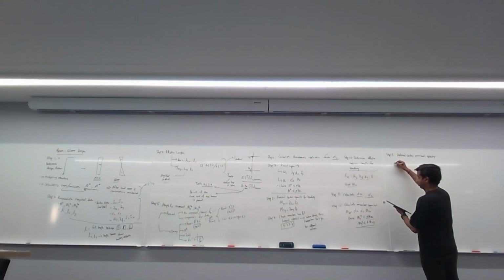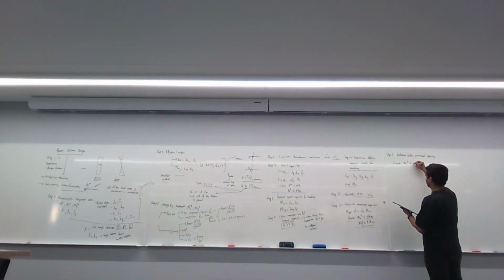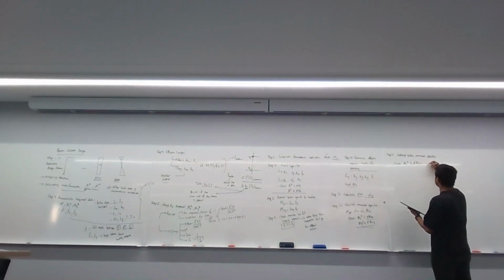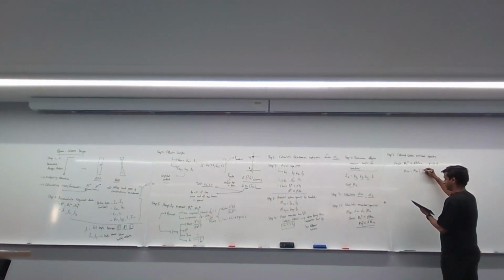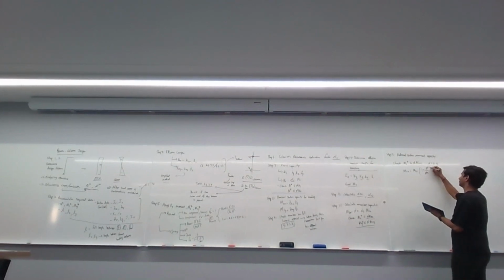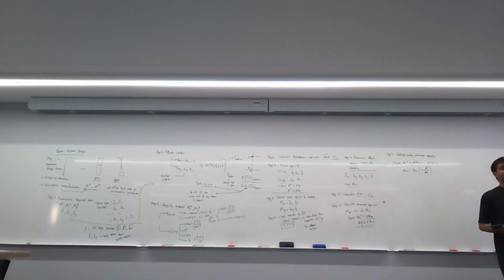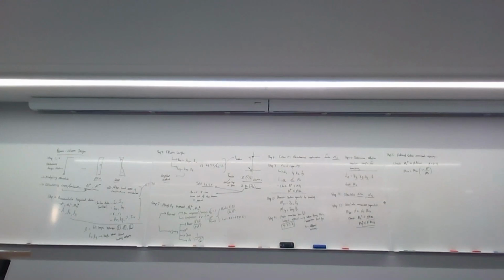So you check Mx star less than or equal to phi Mrx, where phi is equal to 0.9, and Mrx is equal to Msx, 1 minus N star over phi Ns. Okay, so the reason why you're doing this check from step 13 onwards is because you're taking into account the fact that bending is not happening alone.